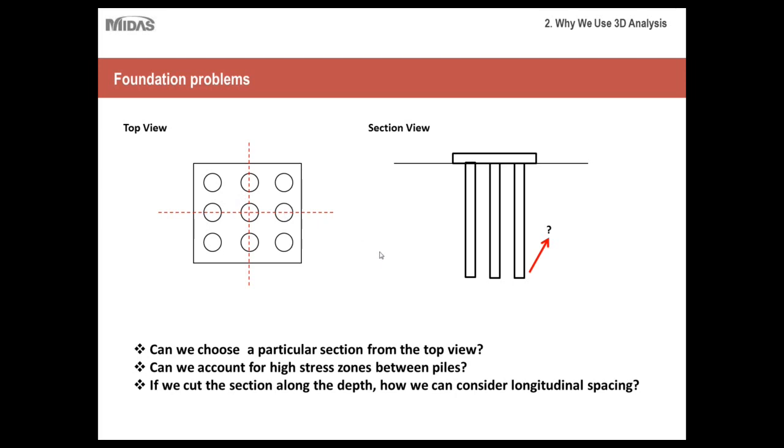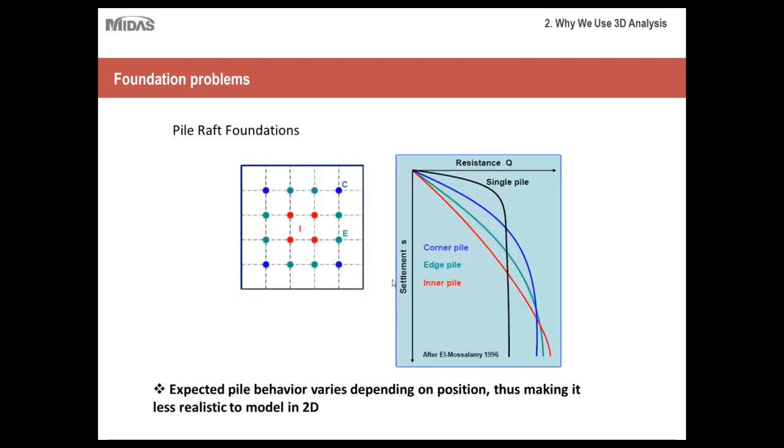So just keep in mind that with group pile foundations, even though the geometry itself may be symmetric, the conditions are not. That's why foundation problems, specifically group pile foundations, are typically modeled in 3D to get the most accurate results.